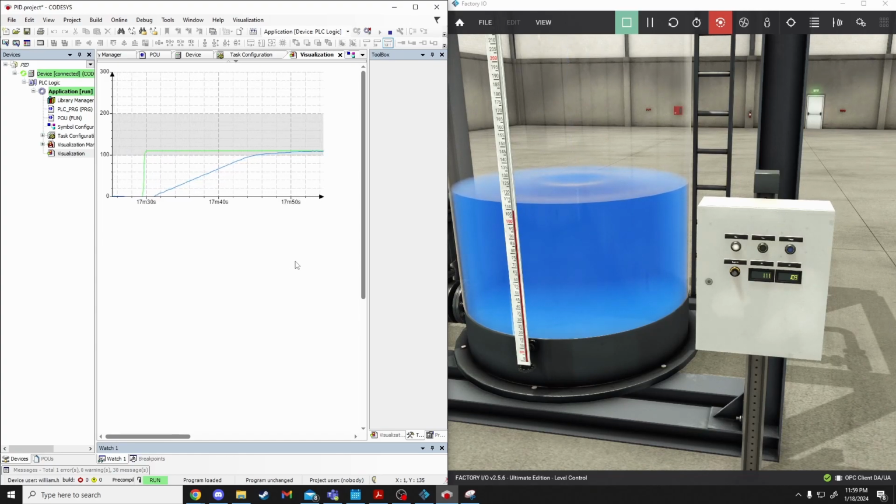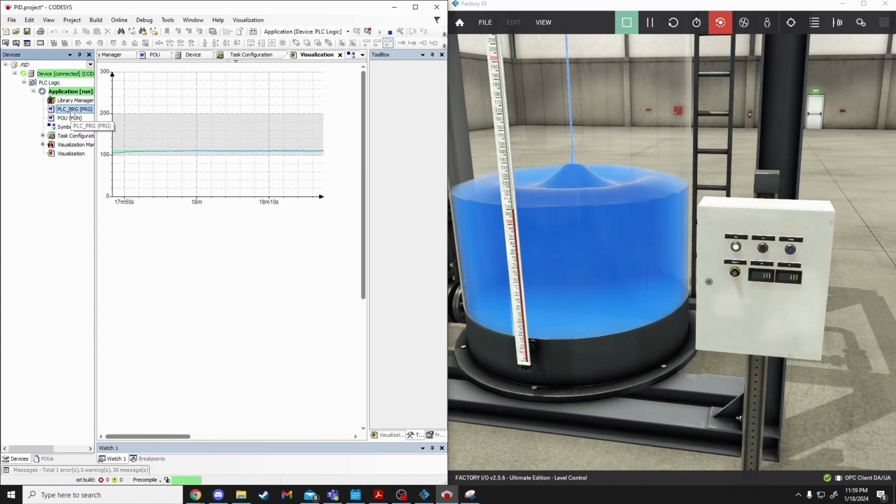We're at 110. 111. Ooh, that is fantastic. What's it going to do now, though? Oh, we're starting to get some oscillations here. We've got this steady state error. So you see that's getting worse and worse. It's got steady state error and it's starting to resonate.